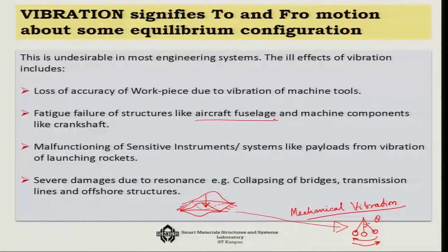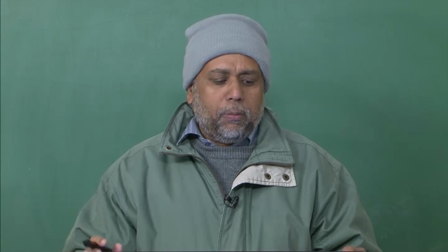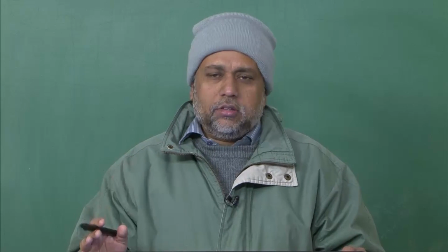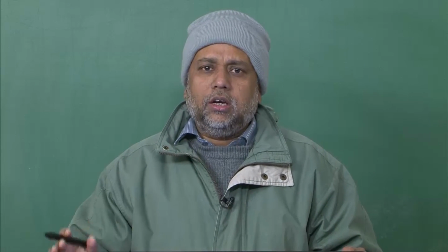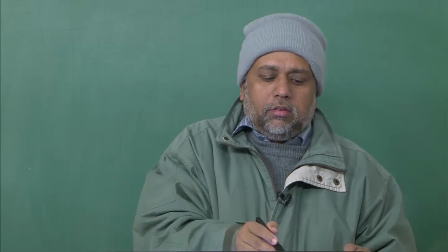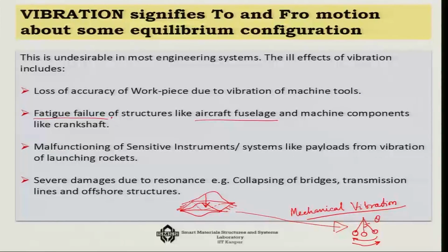So, if a structure is subjected to repeated tension and compression, tensile stress and compressive stress, that's how we define fatigue loading, or a variation of tensile stress or a variation of compressive stress, any one of these three variations let us say, then the cracks inside the structure get sufficient energy to propagate, and in the long run the structure fails, which we call fatigue failure.